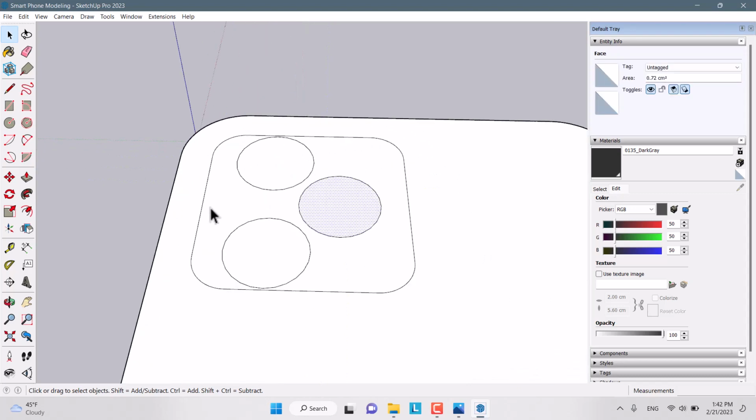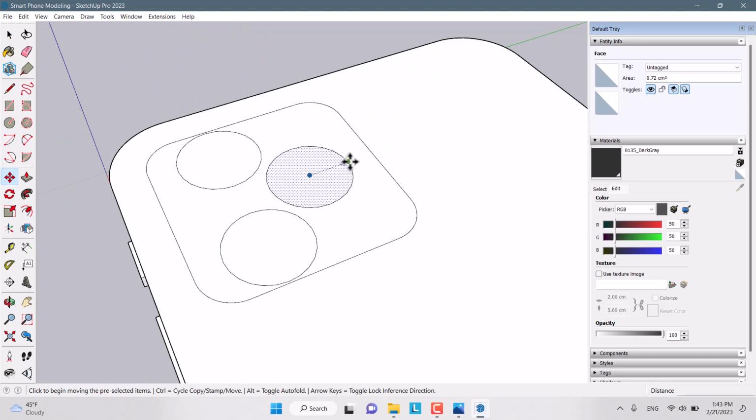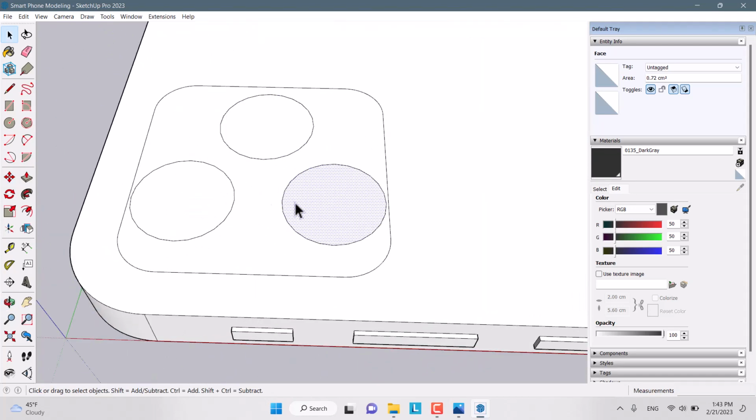I want to move this circle a little bit in the green direction. So I choose the center of it and I click on it. A little bit go to the green direction, green axis, about 2 millimeters. And I want to close these two circles to each other.